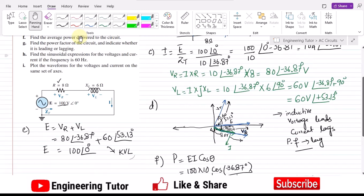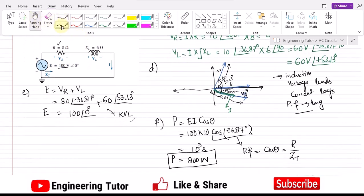After part F, we have to find the power factor of the circuit and indicate whether it is leading or lagging. So again, as we have already found out, let me call it G. I have told you that that is cos of theta, the cos of the theta of which the voltage and the total current has. So cos of minus 36.87 degrees.